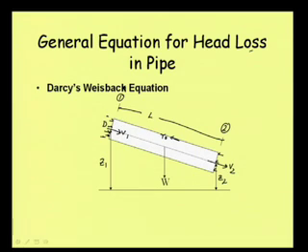Suppose this pipe is carrying the fluid and the weight of the fluid acts in the vertical direction, and if this angle is theta, then the component of this weight in this direction we can write as W cos theta, because our pipe is inclined and we are taking the angle with the vertical. So, this force is W cos theta.